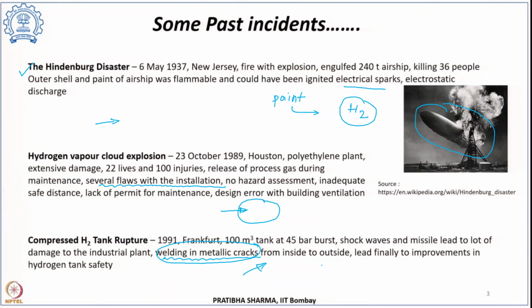When the material got embrittlement due to the hydrogen or compressed hydrogen, the material behavior changes from ductile behavior to brittle behavior. Brittle behavior means sudden failure, or sudden rise of the crack, or sudden crack propagation. This sudden crack propagation may cause the hydrogen tank rupture.